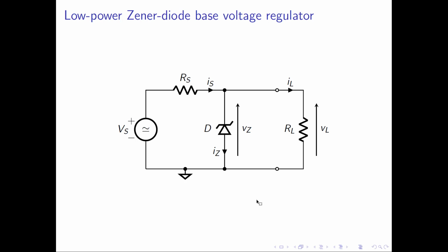Now, in reality, these circuits wouldn't be used very much. We would probably buy an integrated voltage regulator, but at a pinch, for the right sort of application, this will do fine for, like I say, very low power applications. Later on, we'll have a look at transistor versions of this, where there is some feedback. The presence of the transistor allows us to have much larger load currents, and we'll have a Zener source providing voltage reference for a much more sophisticated voltage regulator.